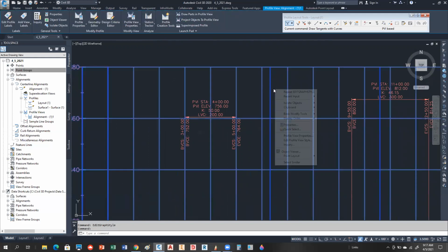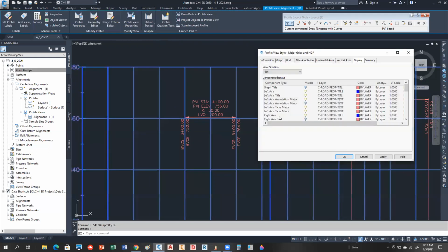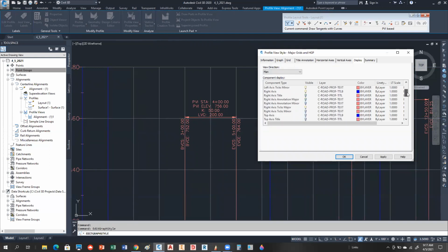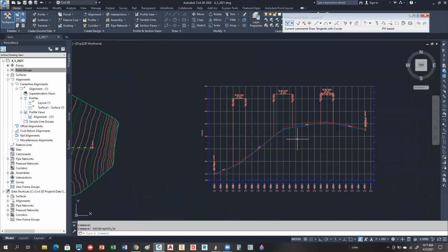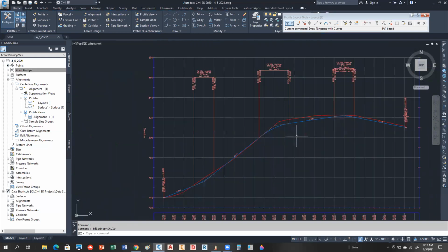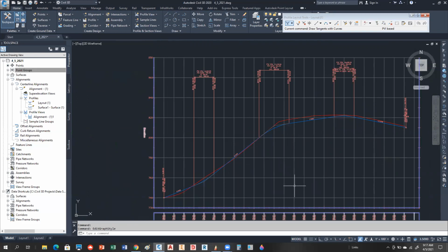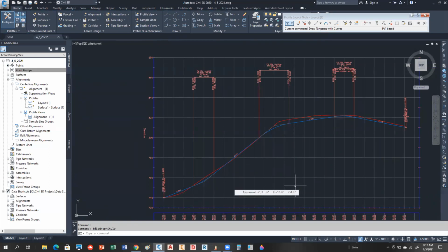Let's see if we can find these geometry guys. They're also in there. I think they're horizontal geometry marks. Let's see. Profile hatch. There it is. Grid at horizontal geometry. So if you don't like those guys, you can just toggle those out. So you clean your grid up a whole lot more. That's kind of the bottom line. You don't want a lot of busy work on there. Particularly on a profile, you can get pipes down here, so you don't want a whole lot of that other stuff cluttering it up because every line just makes it look that much harder to see.